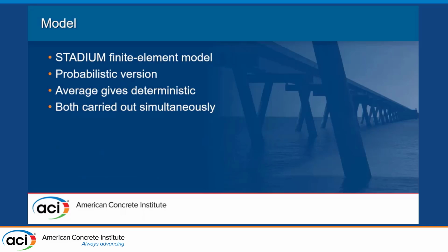The model that was used is Stadium, which is a finite element model. I'm not going to describe the model here, but it's predictive. So instead of reproducing chloride profiles, we use the real data from the mix, from the binders, the geometry of the structure, and the exposure conditions, and we recreate what would be the chloride profile. Of course, normally it's validated with real chloride profiles, but the idea here is just to show what we can get with that type of model.